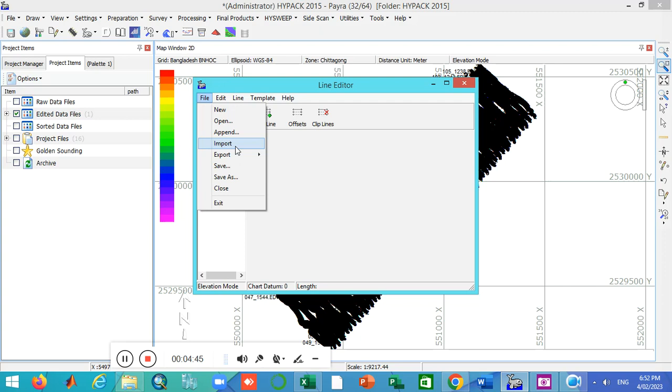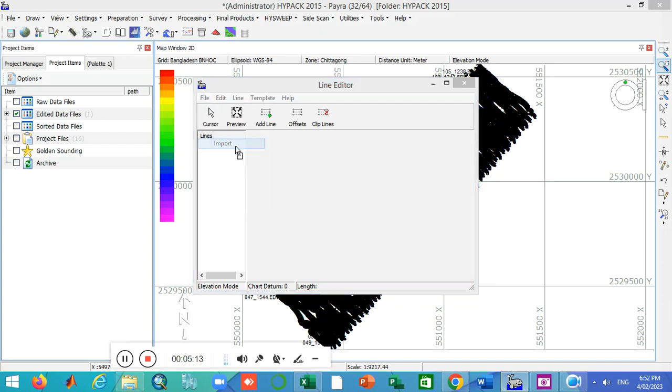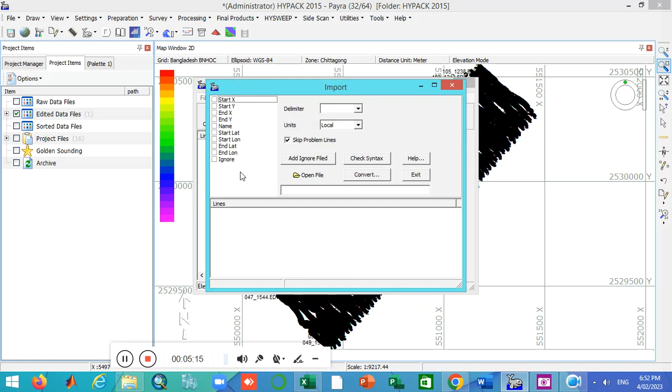Most design sections are trapezoidal sections, which have a fixed bottom width, the center line at the center of that bottom width, and also a side slope, which may vary from 1:3 to 1:6. 1:6 is mostly used for the sea portion, and 1:3 and others are used in the river portion. Actually it is a common practice, not a rigid rule. Okay, if I want to import, you can see I import such things in this fashion.